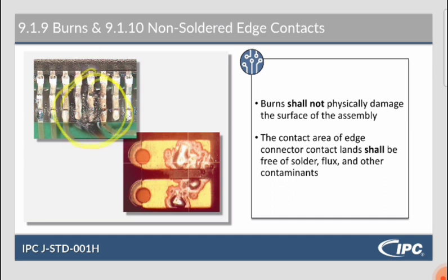That is completely damaged. The contact area of edge connector contact lands. So this is for a connector, and this is not supposed to have solder on it. This shall be free of solder, flux, and other contaminants. This would be a defect for all three classes. That is considered FOD.